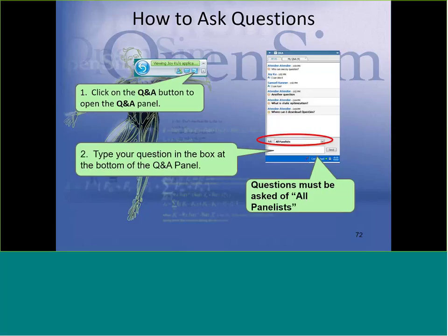So there may be a way to simplify the wrapping at those deep knee angles, but I would take a really close look at the muscle paths and the muscle moment arms at the knee angles that you care about. And if you see a discontinuity in the muscle moment arm, if you plot it, you'll know that it fell off the wrapping surface and you need to fix it.